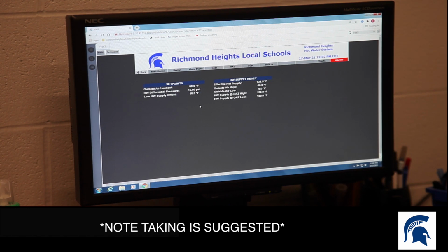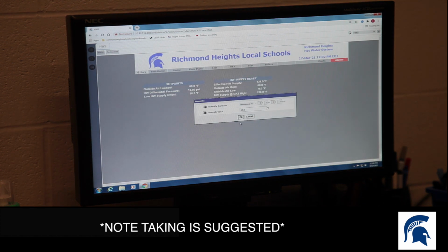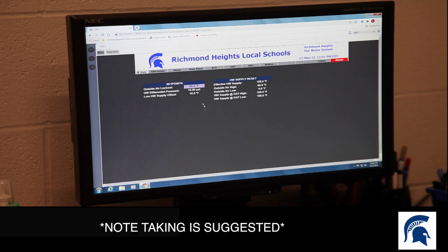And if you use just the regular override, then you can set it to expire. If you use the emergency level, then that doesn't have a time expiration you can set. It's just permanent. So I could do the same thing if I redid it for 55 and overrode it and then came back, override, 55. And then push auto, and it'll stay like that permanently.